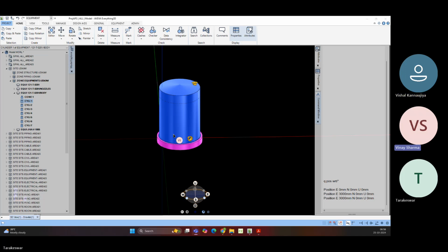Normally in the industry, you need to calculate the MTO by macros, or manual MTO. But manual MTO is not exact. When you create the isometric, the BOM will be generated. So through that, for example, in some isometric or in some piping, you put some items as non-reportable.